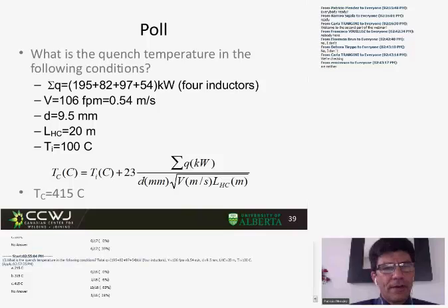This temperature you have just calculated is given a process. It tells us what temperature we think we are entering the quenching cage. If we wanted to change that temperature, for example to increase it, we could increase the heat of the inductors. If somebody asks about a new product with a different wall thickness, we would know what to expect, and we would know how to make sense of changes in mill speed. Typically, there is very little we can do about the air cooling length.